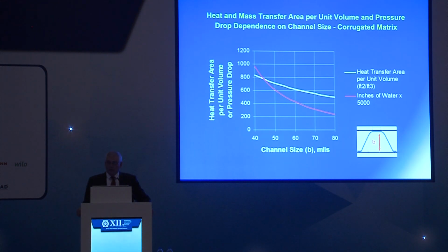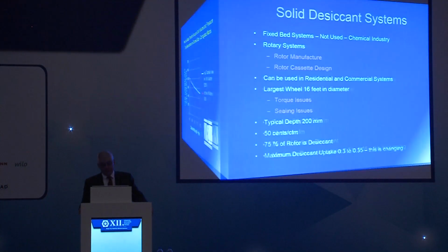However, with these systems, you have to be careful with dust and dust accumulation. That's why you'll mostly see them operating in a counterflow mode, because that will essentially keep them clean. Or some people have developed systems that can be washed down with water, that don't deteriorate with the addition of liquid water to their surfaces. But that's a different topic, not the topic of this conversation.